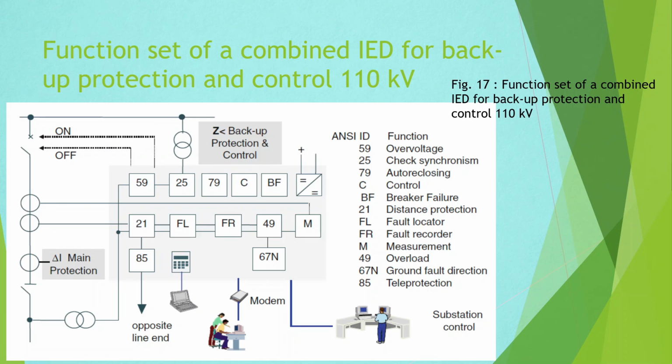The automatic reclosing function is mainly used in networks with overhead lines. Here, experience shows that about 85% of the faults are temporary in nature, caused by atmospheric lightning, wind and phase conductor swing, tree contact, birds.